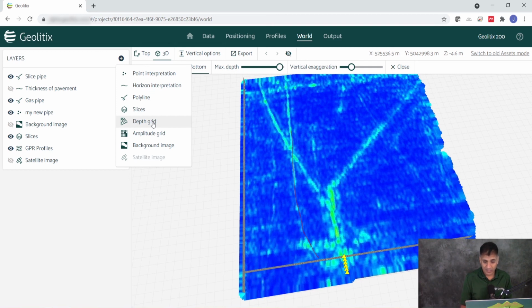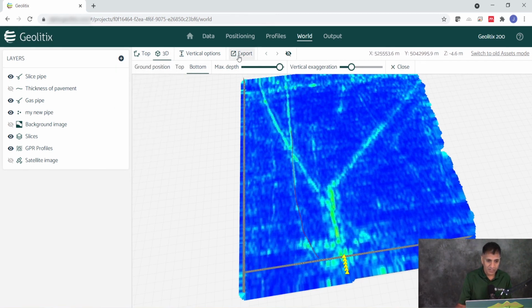As well as bridge deck analysis, everything that you'd need to do with your GPR data set. Now, we won't go into all the different export functions, but I will show you that we can export as a DXF file or as a KMZ, and literally it comes up with a little box here, exporting files, it's zipping everything up, and it outputs it as a KMZ file, which we can then go into Google Earth.